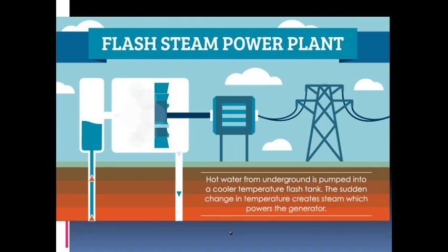In the case of a flash type steam power plant, as you can see here, from the hot water, flashes of steam are generated as indicated in this figure, and these flashes of steam will turn the turbine to generate electricity. So high pressure water comes up in the production well, and part of the liquid is boiled to form steam which comes in flashes, and after this flash is ejected, the pressure will be reduced. Effectively, they will have a rotation of turbine and electricity generation.